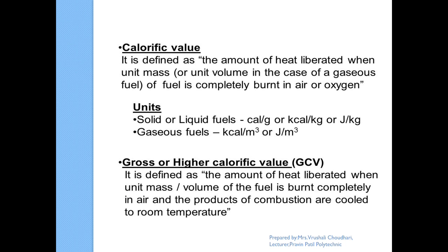Calorific value is defined as the amount of heat liberated when a unit mass or unit volume of the fuel is completely burned in air or oxygen. Units for solid and liquid fuels are calorie per gram or kilocalorie per kg. For gaseous fuels, it is kilocalorie per meter cube. If the calorific value is higher, the fuel is of better quality.